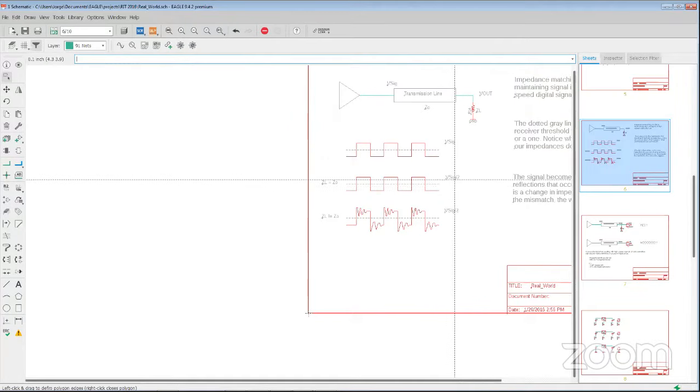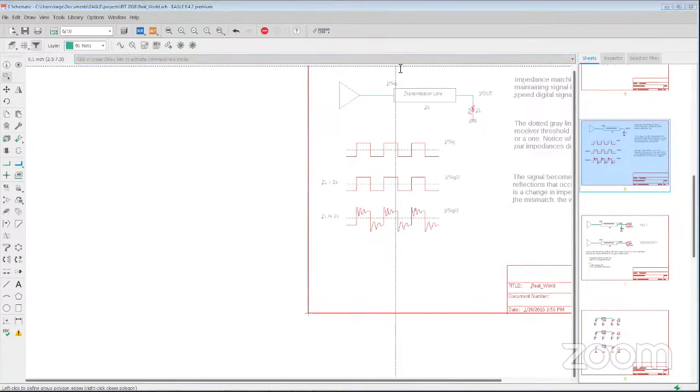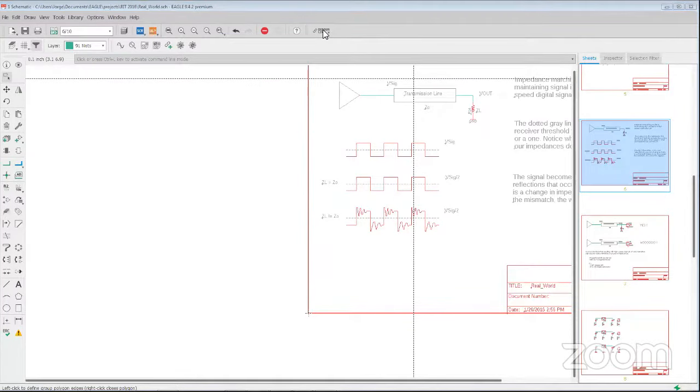And I just mentioned it because a lot of people, that sounds funny to them. Like, why wouldn't I want maximum voltage across? And the reason is that the signal you're interested in isn't necessarily voltage. You want to make sure that you have the maximum power transfer, because that maintains the quality of your signal going through. If you're dealing with audio, it doesn't matter. You're dealing with 20 kilohertz signals at most. Your interconnects are transparent to that. But that's why I mentioned it, just because many people, when they see that V over 2, wonder why they would want that.